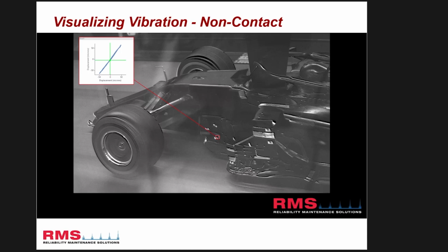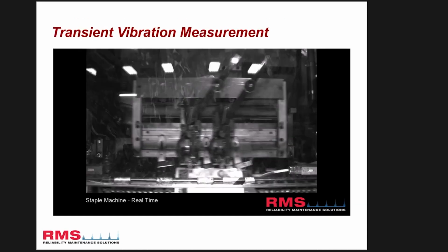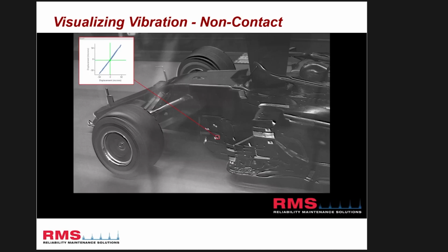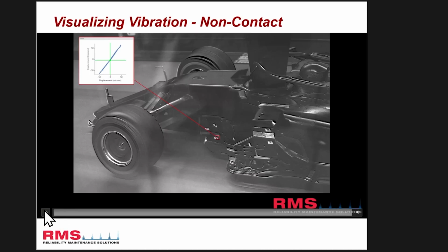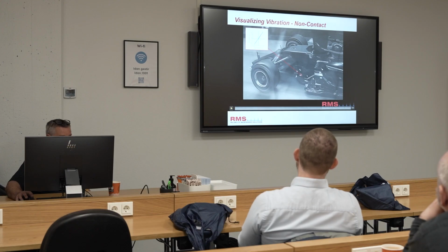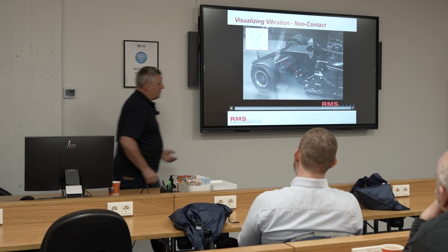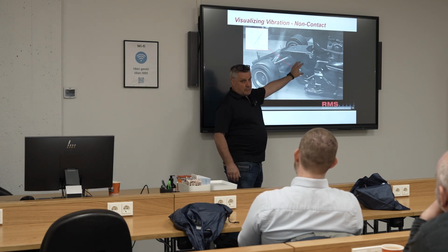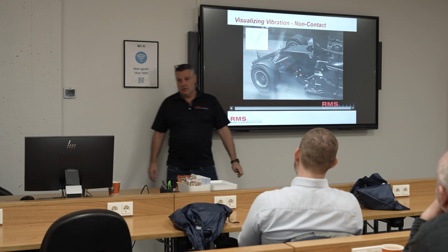But this was something that we showed them we could do. Oh, sorry. That would also be a case of affecting the outcome by measuring. Oh, of course it would, yeah. And that's another point. It's a good point, because obviously by putting the weight of an accelerometer on a plastic component like that, we're going to change the resonant condition and the natural frequency of that component.